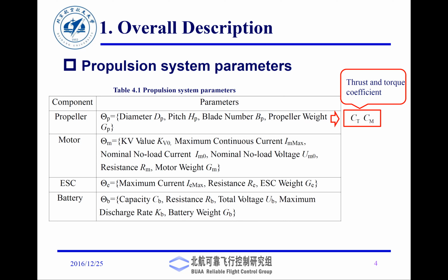It would take off as a helicopter, and in mid-flight, the rotors would rotate, and then it would fly like a plane. So it can hover in place, but also it would be as efficient as the fixed wing state. Initial V-22 accidents happened because of the vortex ring state. In helicopter mode, or when it transitioned from the flight mode, it came down so quickly. It lost altitude so quickly that it destabilized the aircraft.